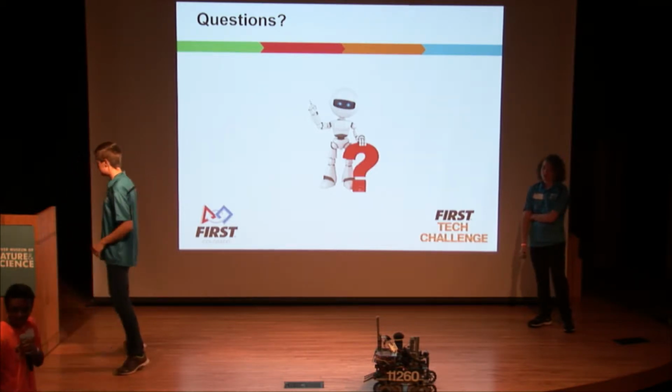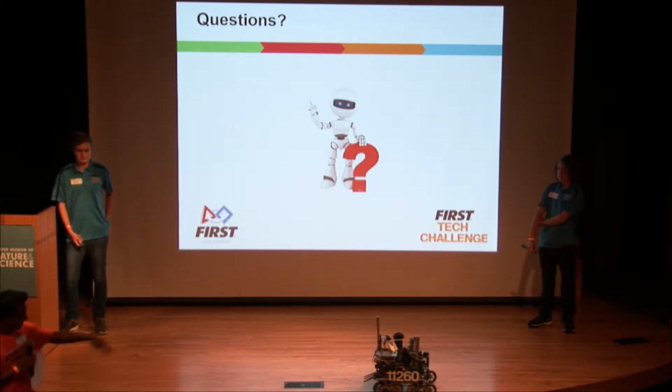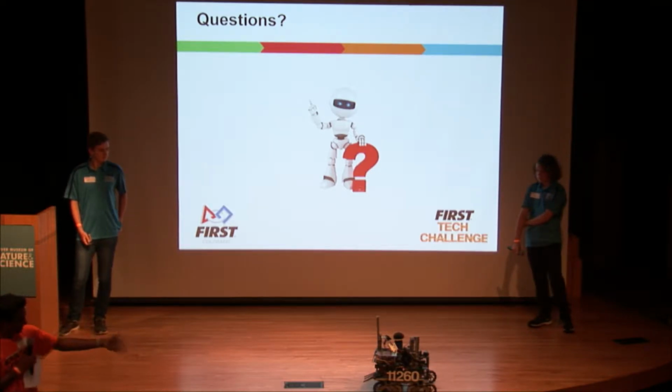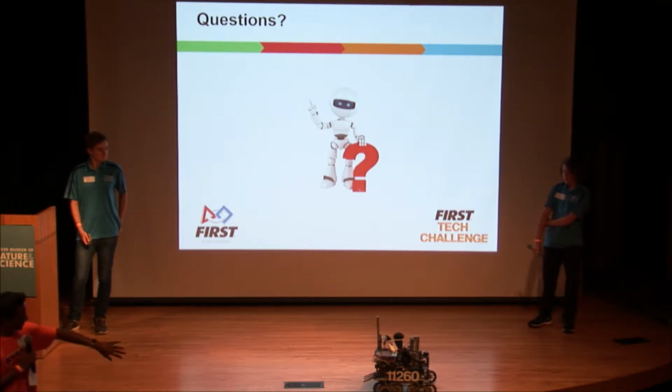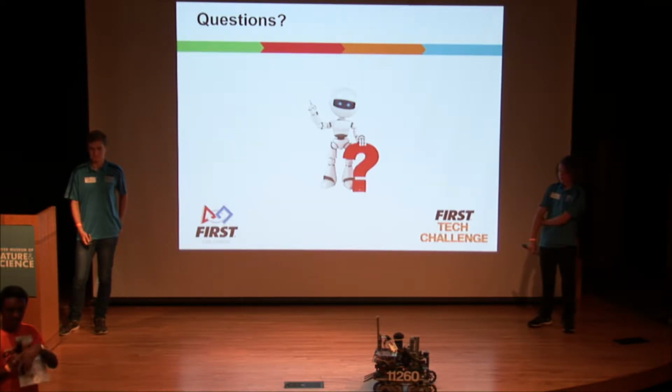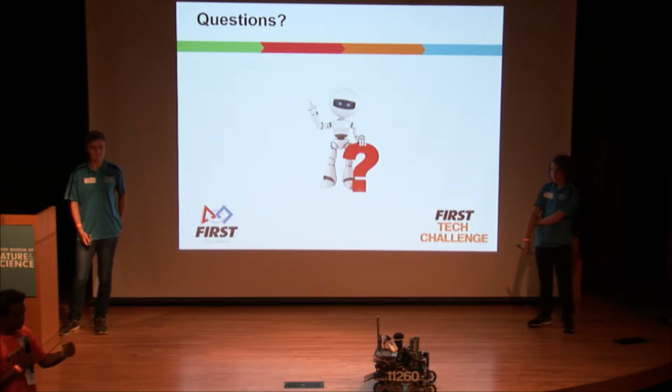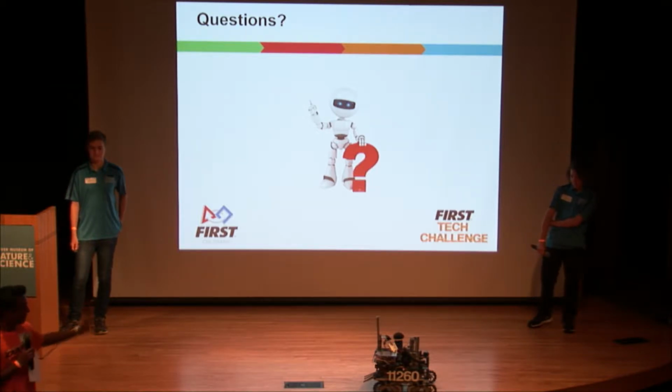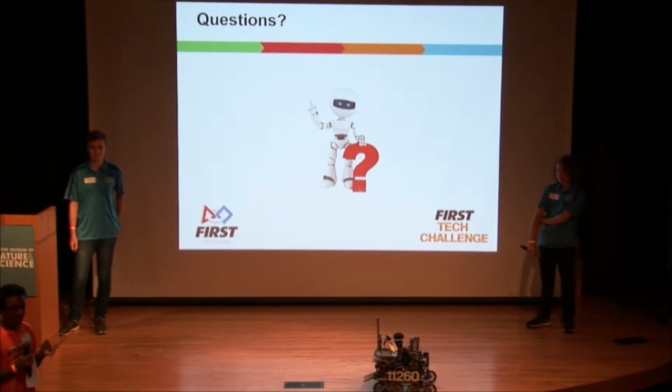Yeah. So to add on to that ESD thing, what you can see is they added plastic on the outside of their robot. It looks good, but it also is not a conductor. So if another robot bumps into you, then the static doesn't go through to the metal. Another thing is the material of the field and the material of the wheels: if they're closer together, it creates less static. There are static charts online where you can see what materials conduct static.